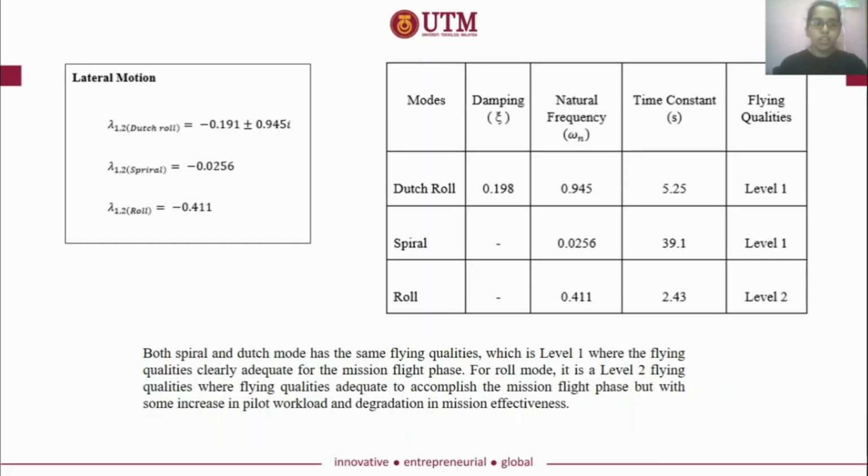The flying qualities depend on the type of aircraft and the flight phase. The type of aircraft is classified into 4 classifications depending on the size and the control characteristic. Flight phase is characterized in 3 different phases depending on the terminal or non-terminal flight.